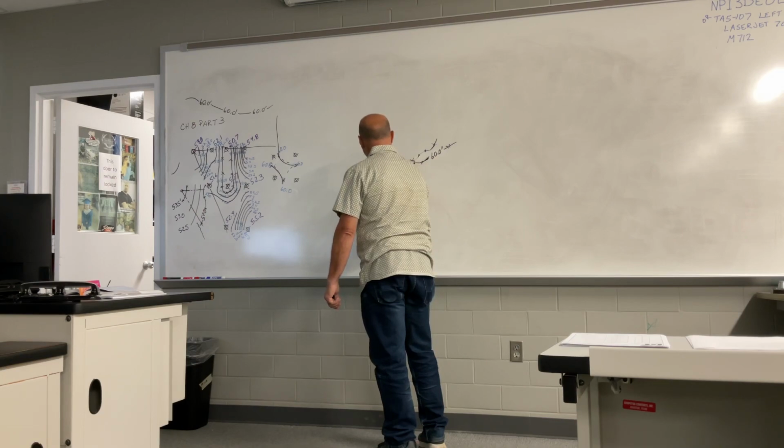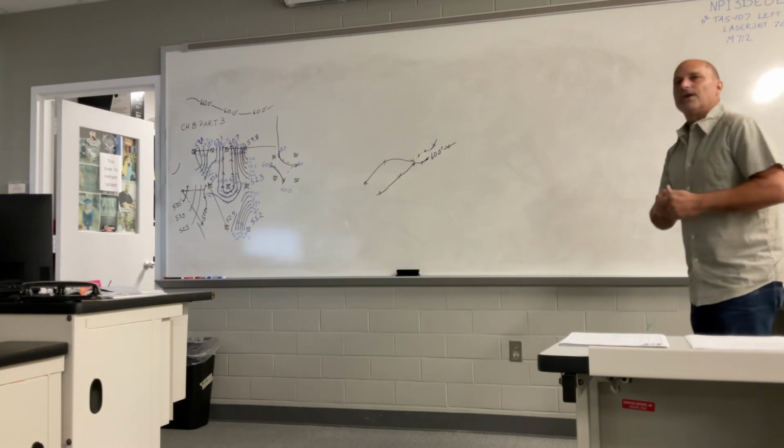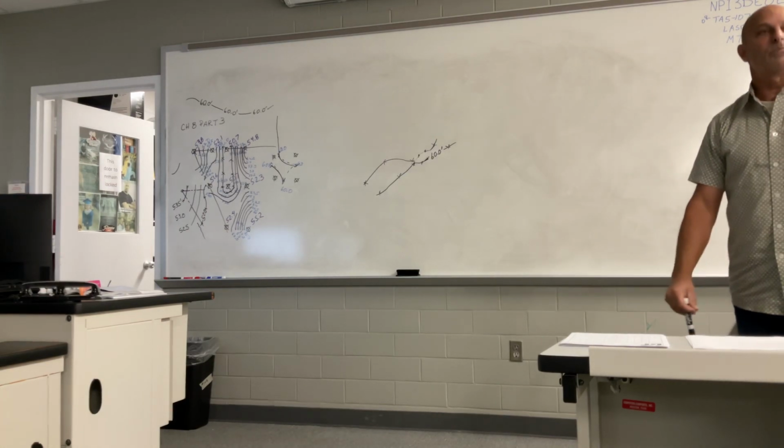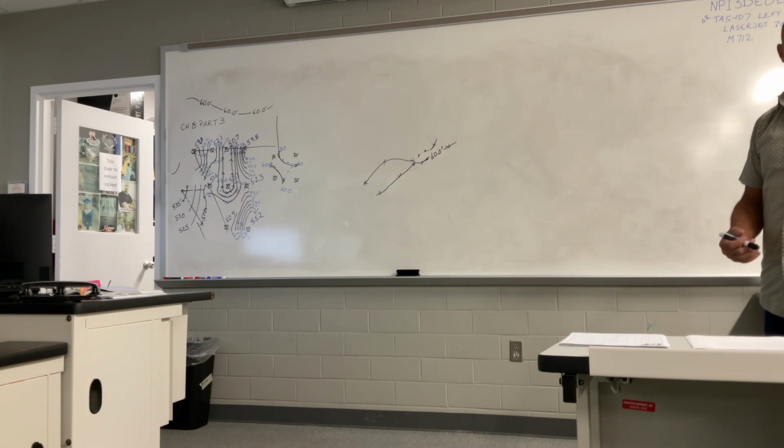That spline now shows back up. Whereas if you use the break command, you've got to go back in there and manipulate and draw that spline back in that area. So I recommend you do multi-line text and use your text masking to do that.